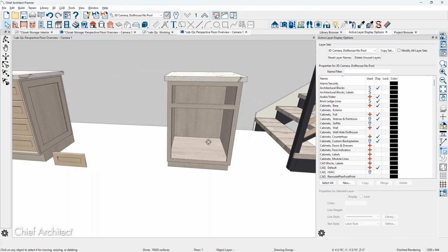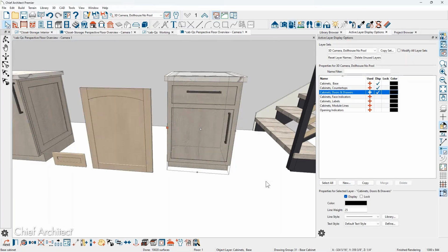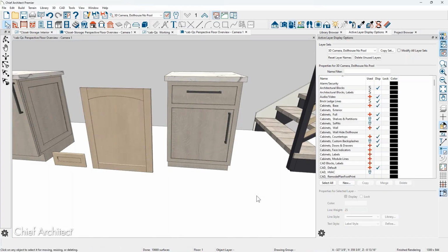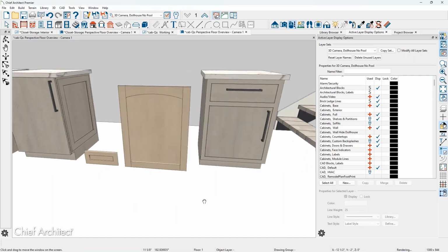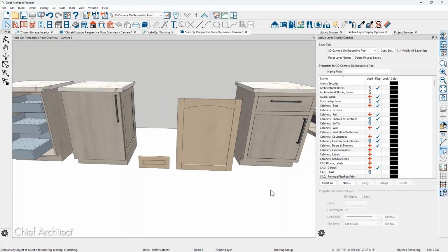So if you added the doors, they would sit flush inside of that. So I have to draw everything behind it. Usually I just draw things in elevations, because like your picture to the left, everything wants to sit flush with that face frame. So I need to modify depths, and I need to modify the offset so it sits behind where that door is. Okay.